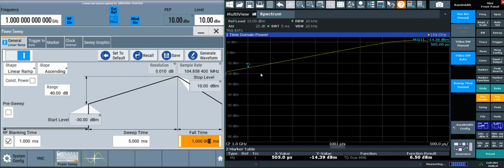And there we have the amplitude sweep. We just need to make sure we have sufficient resolution bandwidth as before. Whenever you have a fast sweep, that should be sufficient there. And if we have too high of a resolution bandwidth, we'll notice we have maybe a little bit more noise on the trace, just since we're allowing too much noise to degrade the measurement on the low end of the signal. But that's really the only penalty we pay.